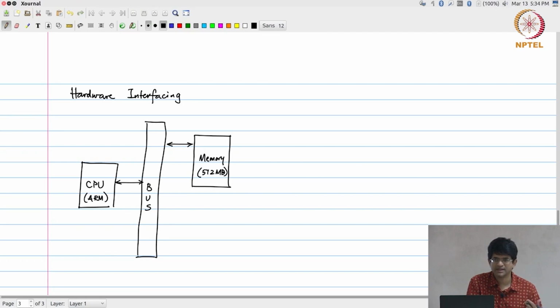Another related disadvantage is the fact that it is dynamic, meaning that it can decay and lose information if you do not keep refreshing it. Okay. So, net result is DRAM is problematic. It is not a very easy to analyze kind of memory. You can't just say I give it an address, one cycle later it gives me back the data. It does not work that way. Okay. But I can have 512 MB of DRAM, I can't even think of having 512 MB of SRAM in a design of this sort.